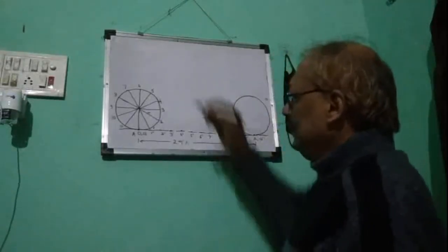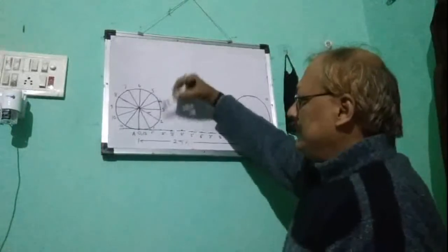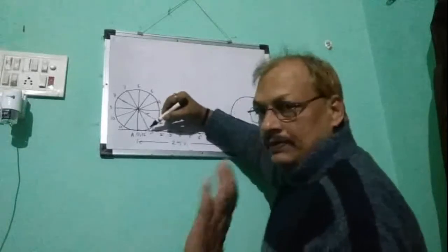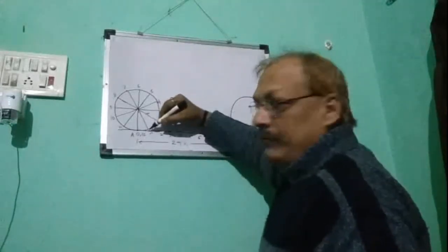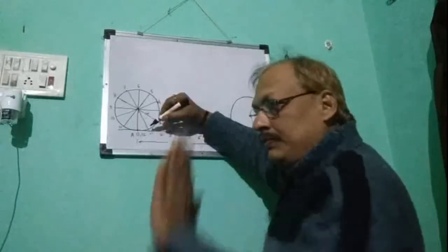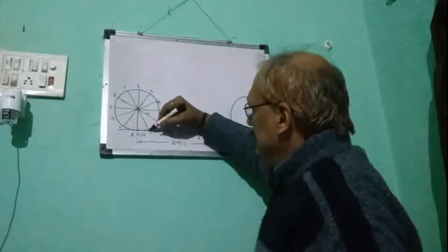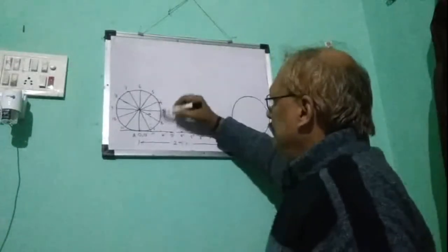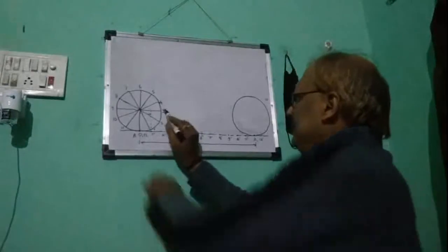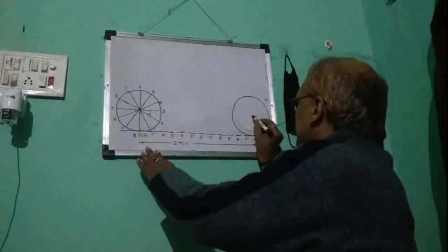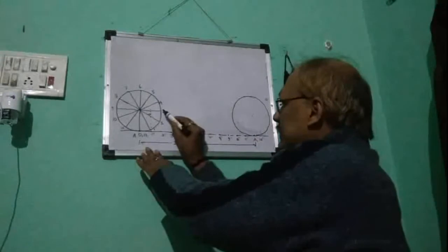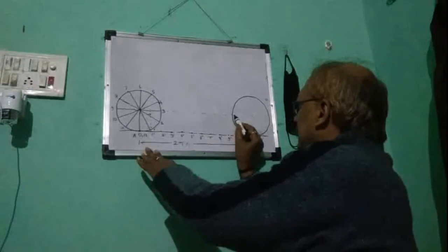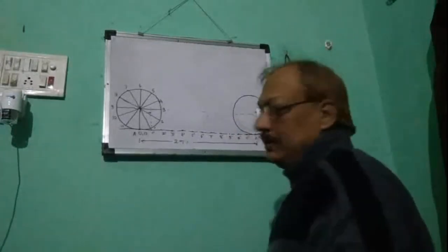Okay. Now we will have to draw verticals through 1 dash, 2 dash, 3 dash. I will make them dotted; however, on the sheet you have to make them with 4H lines. This line we will proceed up to here. All centers will be on this line.